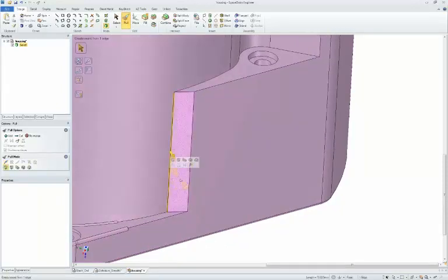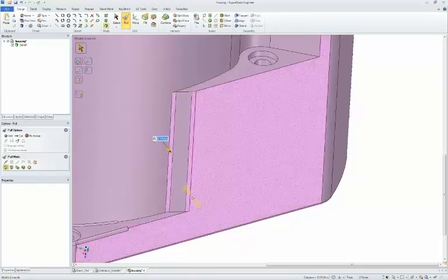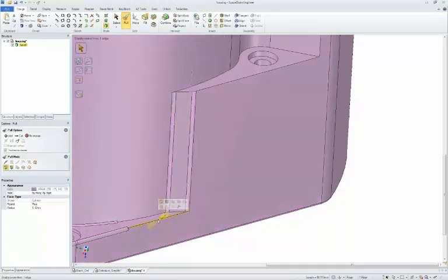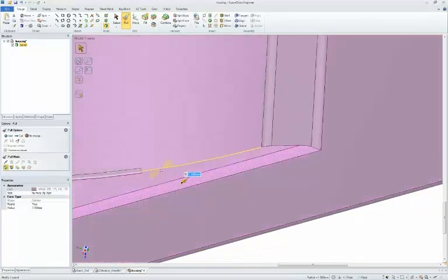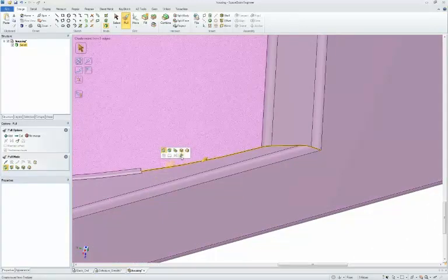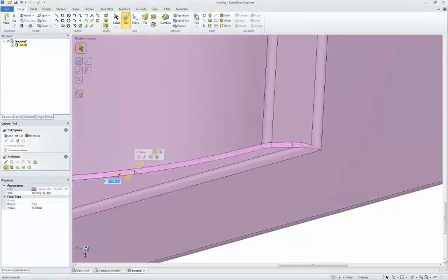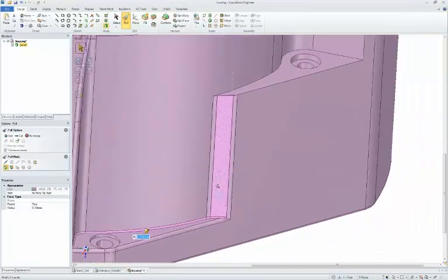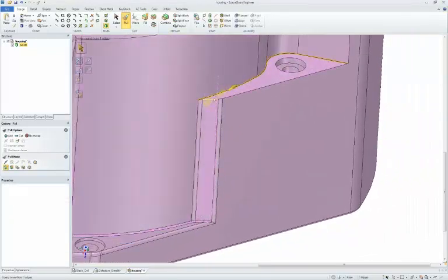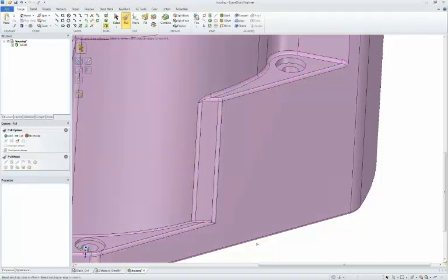And if I want to put some of the rounds back, because maybe you do want the rounds in the model, with pull, you can add rounds. Pull can snap one round up to an adjacent round on the part. So notice pulling a round chain up to an existing round can put some of these rounds back for us. Again, without having to know or care about how the part was originally created or made. Simply pulling our rounds back into the model.